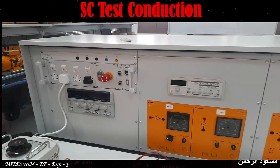In the open circuit test, 220 volt is written on the primary side as the rated voltage, so we applied the 220 volt directly. But on the secondary side, there is no current written in the nameplate details, so we have to calculate it from a particular equation. The rated full load current on the secondary winding is the VA rating divided by the secondary voltage. If you divide by the primary voltage, it will give you the primary rated current.